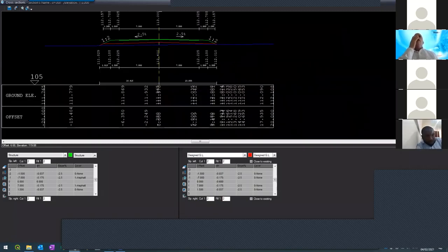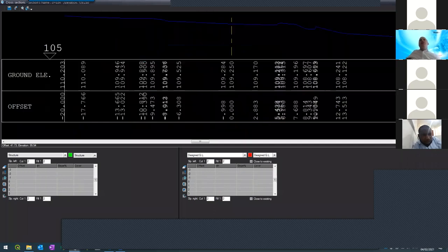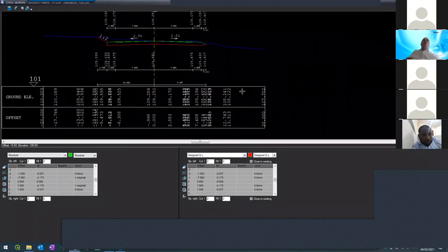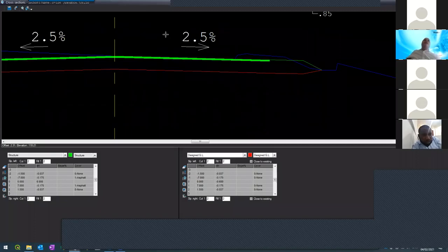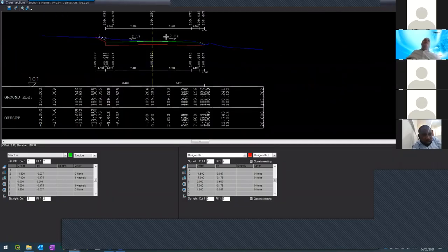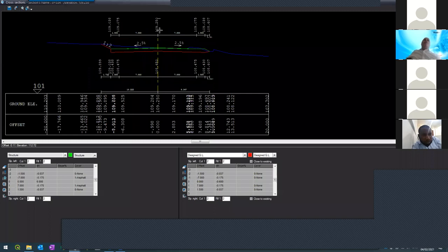Fine. Now remember what I did. I copied from here, went to a section and pasted, then pressed apply and saw the result. But this is not what I want because I have many sections here. So instead of going section by section, look what I'm doing. I'm copying from this first section, going to the last section, and pasting here, and pressing apply. This is the last section, right? And now I'm doing interpolation between the first section and the last section.